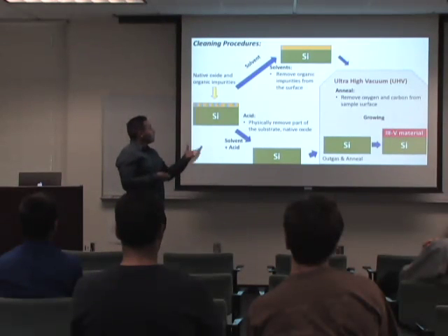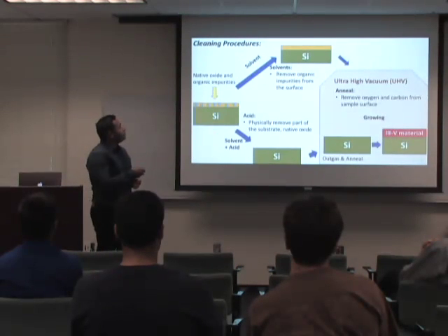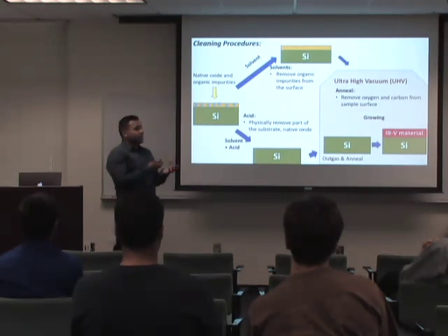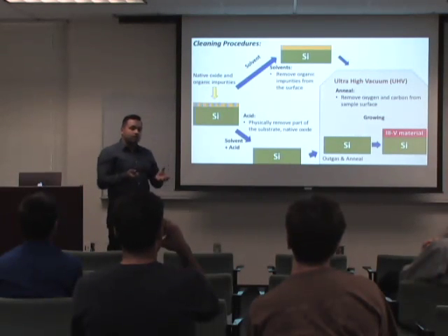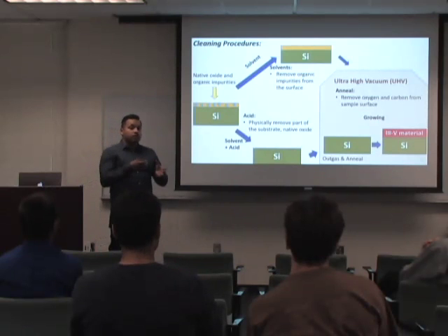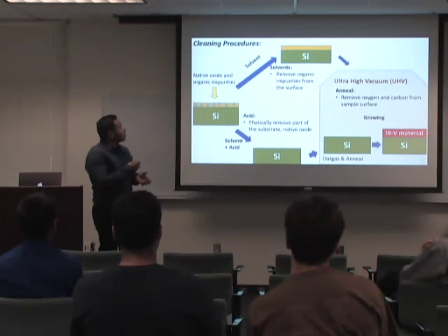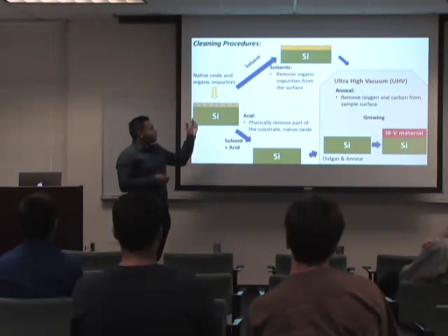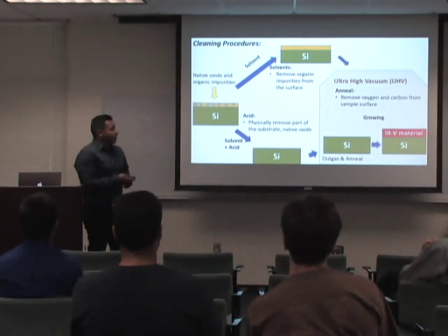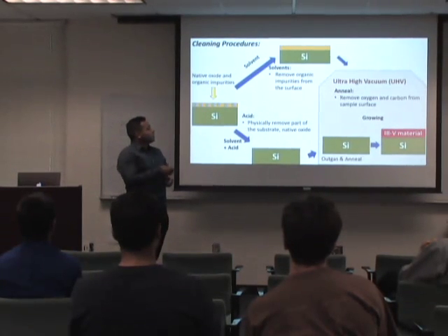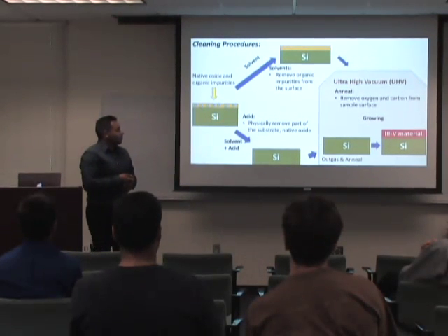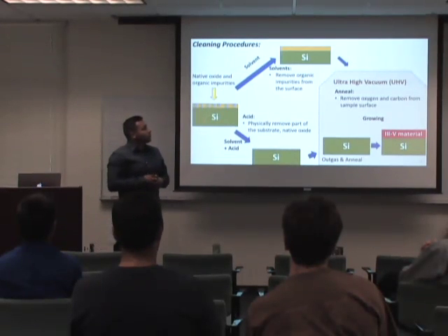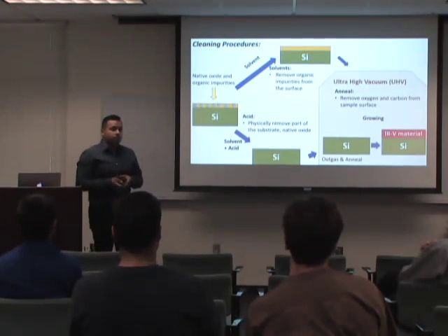So we're going to have this wafer, as received right here. It's going to have some native oxide. This native oxide is coming from the oxygen in the air. And also we have some more organic impurities on top of the surfaces. And we have two ways to clean this wafer. If we use solvent, we're going to remove only the organic impurities on the surface of the silicon.